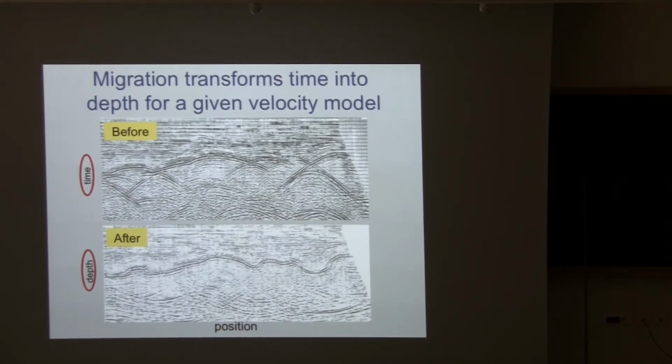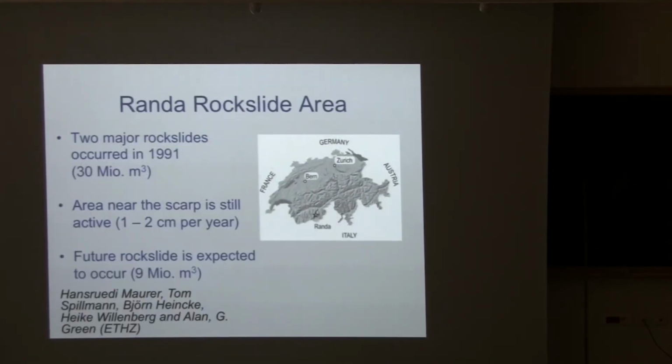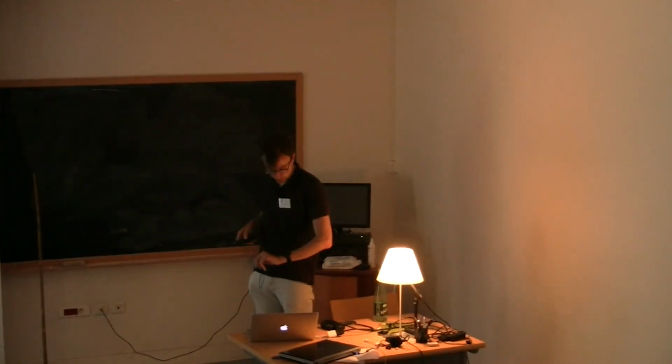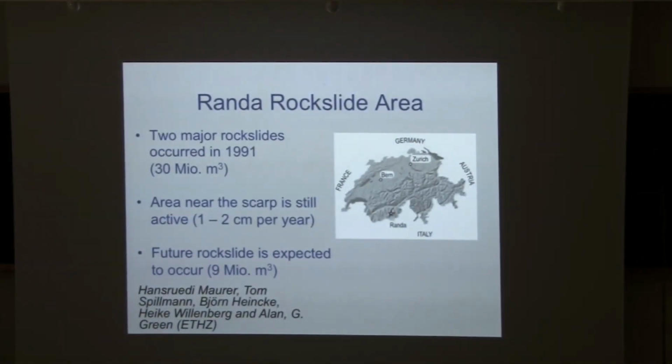So it's a whole science in itself, and seismic reflection is not really used so much in environmental geophysics because it's complicated and it's difficult to get good reflections for the upper 10 or 20 meters. Seismic refraction is more common. This is occurring when you have a layer at depth that has a higher velocity. And when you do this, you can get some nice results.